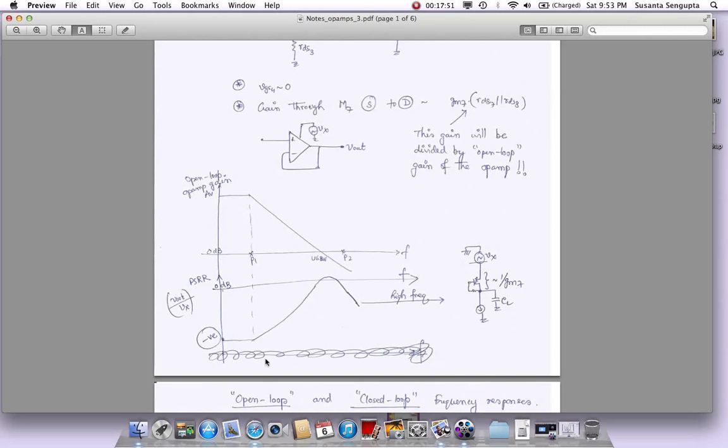Based on that, you can derive your specification: this is the PSRR that I need for this op-amp. If you know that, then you will know what kind of curve you want to meet. Say we design an op-amp with about, as in the previous example, 100 megahertz bandwidth, and we have a plot like this. Is that good enough to get this PSRR plot?